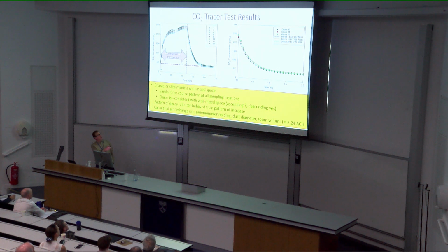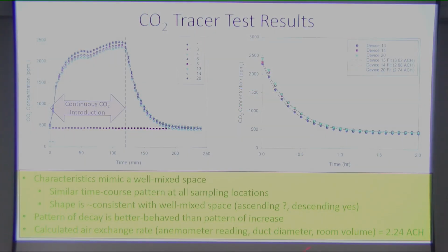So these are 3 of those exponential decays that showed up from 3 of these CO2 monitors. If you look at these data, they are in pretty good agreement, and they look more like 2¾ air changes per hour. So there's some fuzziness in these numbers. I personally would have more confidence in these numbers than that one down in the lower right corner.